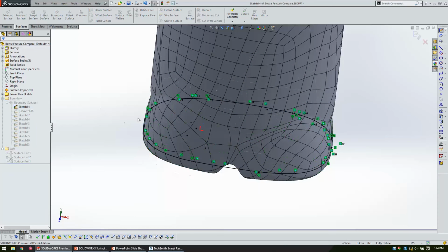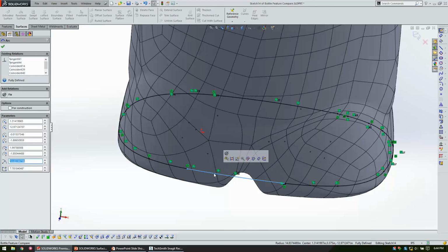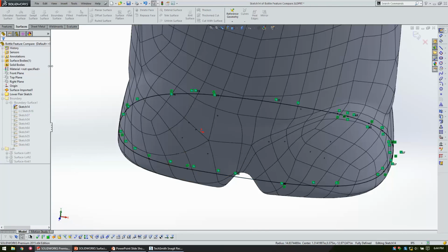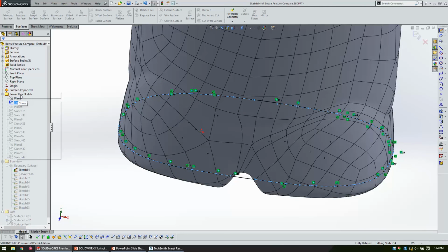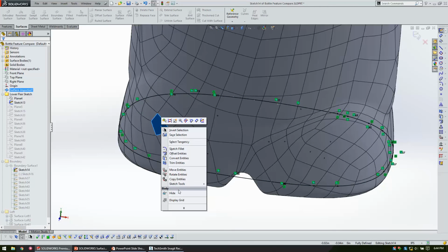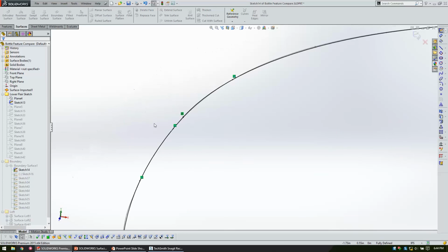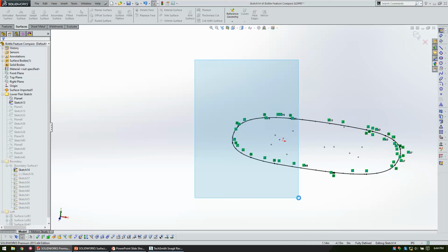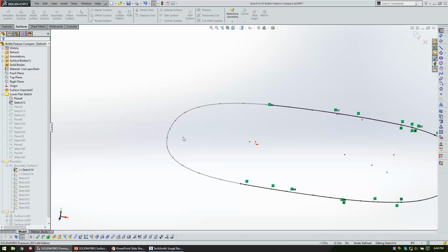So then you take these sketches. This is actually manually overlaid sketches. I just took a bunch of arcs and laid them around the sketch that has a bunch of splines. So I'll try to make this really clear. I'll delete out some of this here in a minute. So here's the first sketch. First of all, never make sketches like this: if you convert a sketch, close that sketch out, start another one. Don't do your intersection spline sketching and then lay your good sketches on top of that. Totally never do that. Just telling you right now.